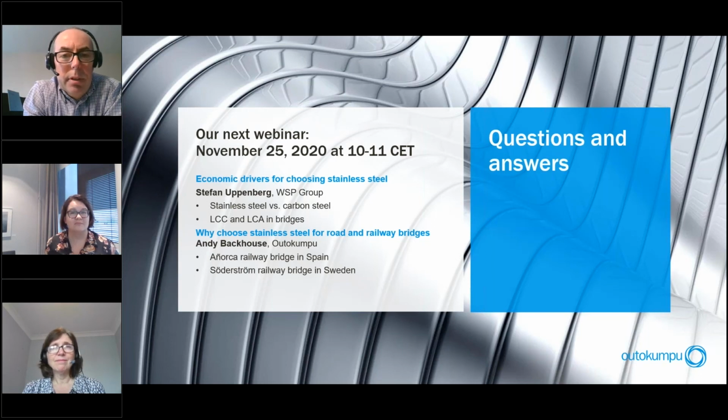From a corrosion resistance perspective, what is crucial is first of all to get the right choice of grade. Grade is absolutely critical for making sure the stainless steel is going to work in the right environment. But surface finish can have a secondary effect too, and in the slide showing our different test sites, we deliberately test different surface finishes just to assess the effect.